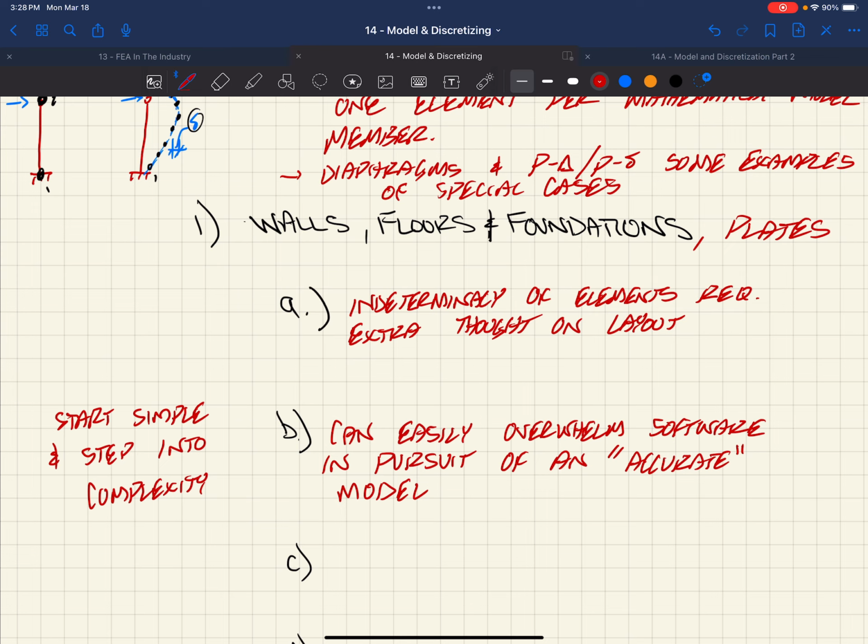Like, I like the fact that the enclosed stairwell in the parking garage to the south of Norm, and connected to Norm, is a very, very simple structure. It's got 2 or 3 bays in one direction, a single bay in the other direction. It has brace frames in one direction and moment frames in the other direction. So very simple systems, very consistent diaphragm layout.